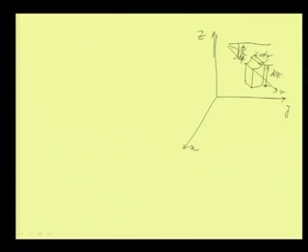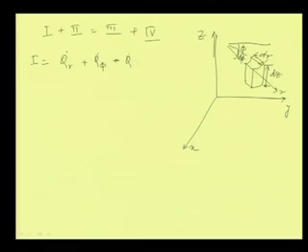If we go in the similar way, for the volume element we again have the four terms: term 1 plus 2, as we have seen previously, equals 3 plus 4, and again here 1 equals q dot r plus q dot phi plus q dot z. So, r, phi, z is the cylindrical coordinate system.